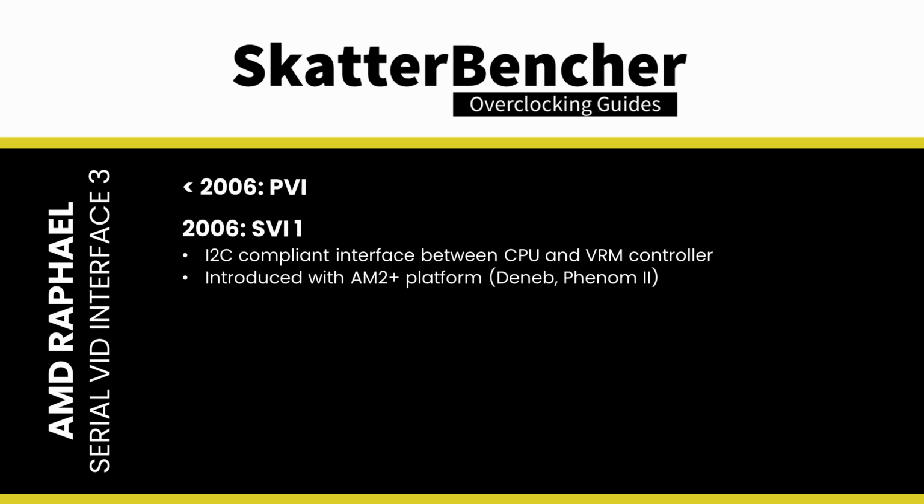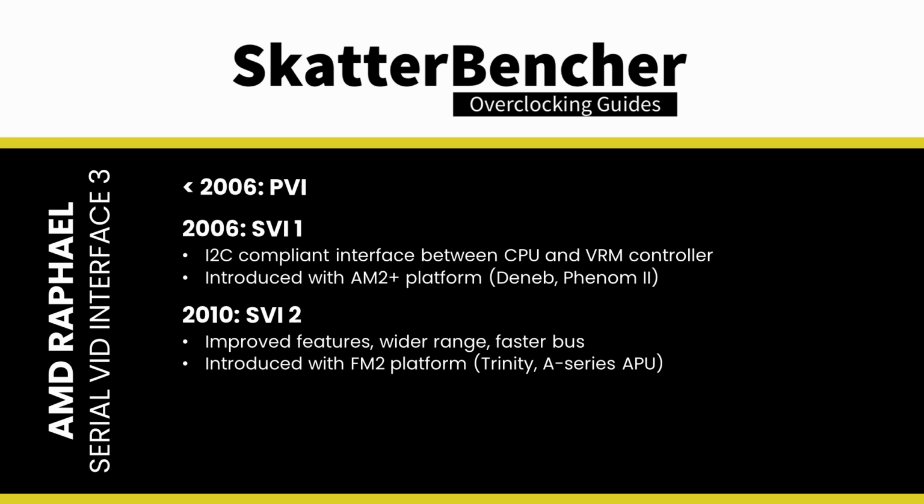The main advantage of SVI is that it provides an I2C compliant interface between the CPU and the VR controller. I2C requires only 3 connections for data, clock, and ground. This removes the need for increasing the number of parallel connections between the voltage regulator and CPU to support additional features and voltage range. The second generation SVI was available to NDA partners in February 2010 and provides a range of features including greater granularity in voltage selection, faster data rate, and telemetry functions. It was introduced to the market with socket FM2 Trinity processors in 2012.